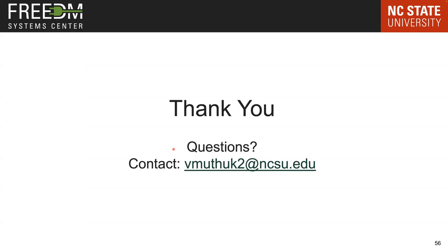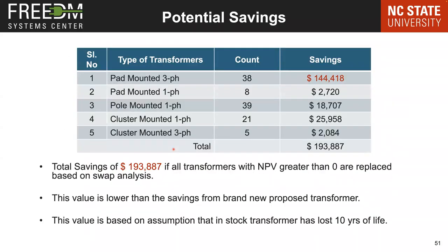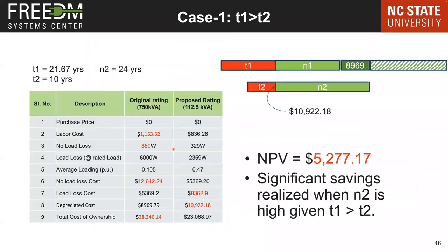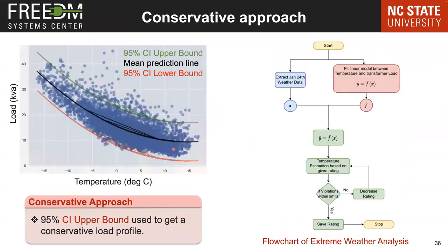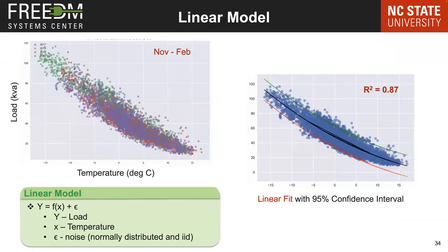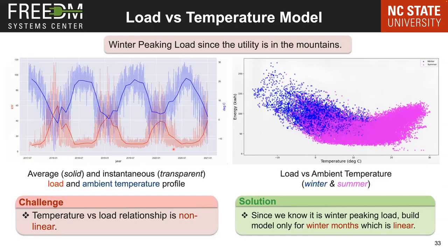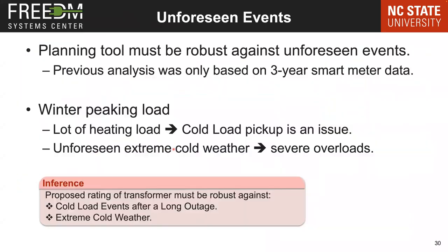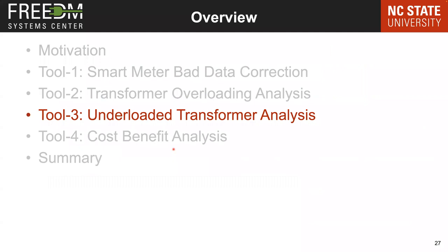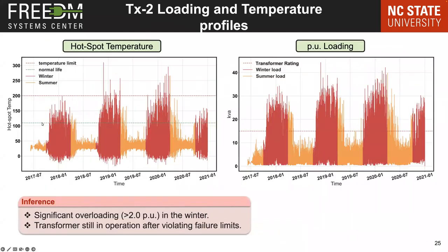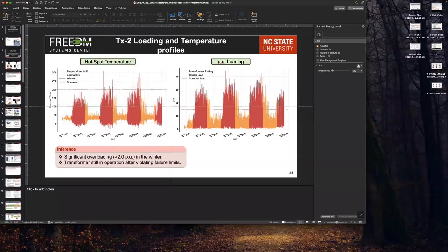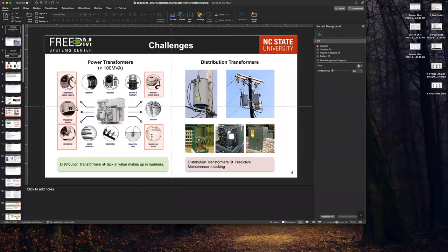So we don't really use that. Apart from loading, we don't use any of these other factors that are mentioned. It is a very interesting topic. There are factors like harmonic discharge, partial discharge due to faults and other reasons. But I'll go back to my first slide. You have dedicated devices on power transformers which look at dissolved gas and look for partial discharge in your transformer.